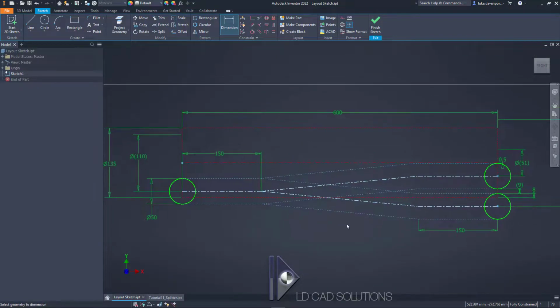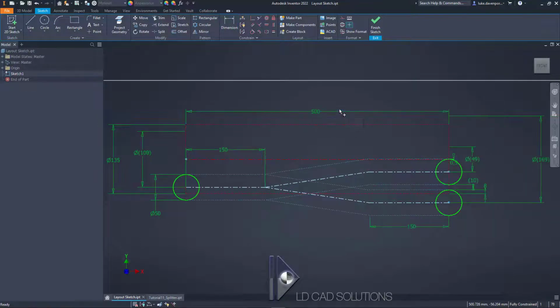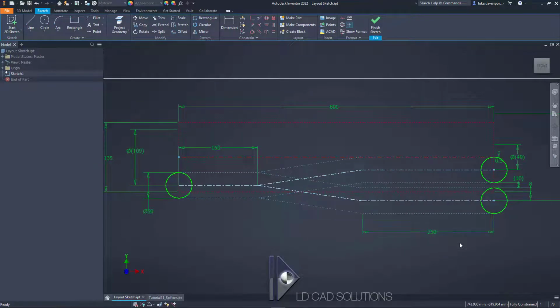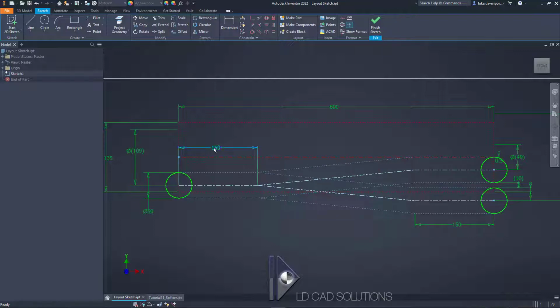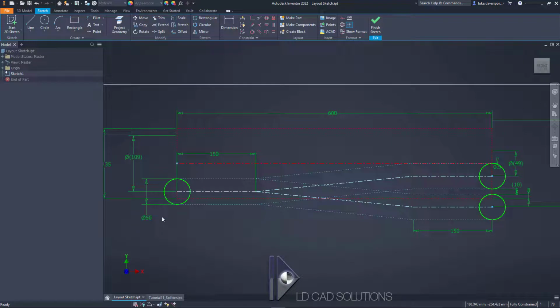Okay, and this sketch is also useful for me to try out some other things. I can see what it will look like as a shorter shaft, 500mm versus 600mm. I can see what happens if I change the length of these lead in and lead out values and so on and so forth, but I'll just leave these as they are with this initial design that I've set up here.